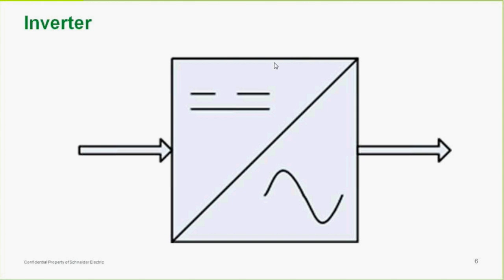The early generation inverters were all what we call a modified square wave inverter. Along came other inverters that had a more true sinusoidal waveform, but all of them have to make this AC waveform happen very precisely. For instance, for North America, we use 60 cycle power, so this thing has to make 60 AC cycles every second exactly. So it's a much more precise development process to make an inverter than a charger. In Europe, it's 50 hertz.